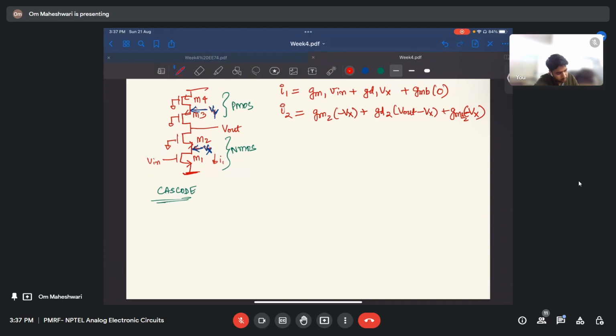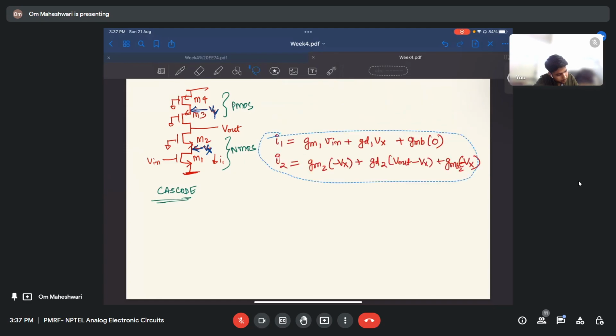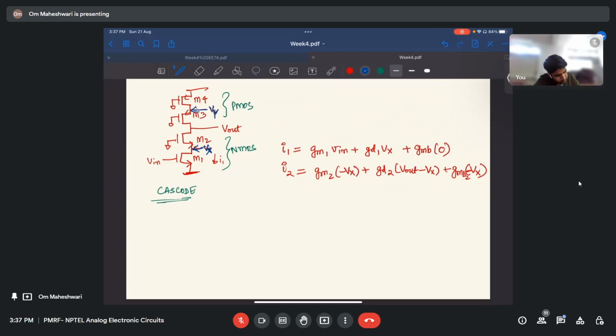So, okay. For NMOS, let me write here. For NMOS, ID equals GM VGS plus GD VDS plus GMB VBS.